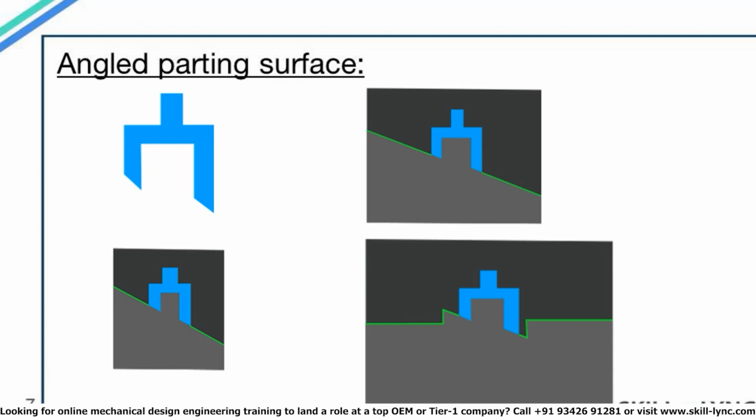And once the profile of the component is captured in the mold block, there is no further point in continuing the same angled surface. Even if you have the complete mold block at some angle, or if you have the mold block at some angle close to the component and then a flat profile, the end result as far as the molding of the component is concerned will still be the same. This addition of flat surface instead of angled surface is done only to allow easier machining.